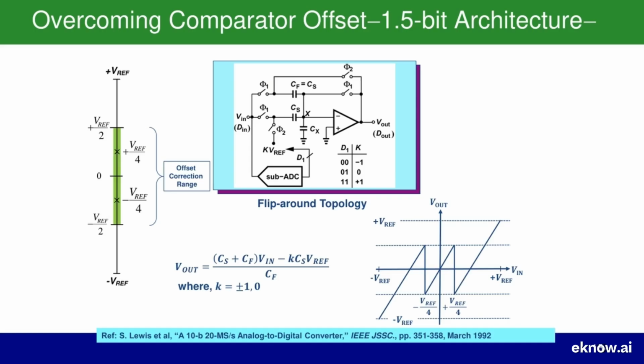For each of these stages, we get one effective bit of resolution for our final ADC output, but we use a 2-bit internal flash ADC and DAC to process the signal. That extra information gives us the redundancy we need to handle errors.